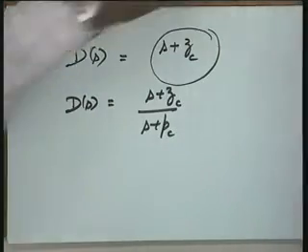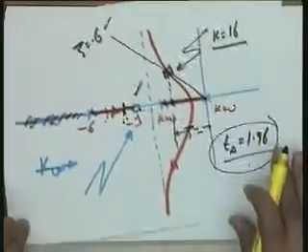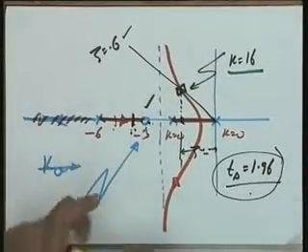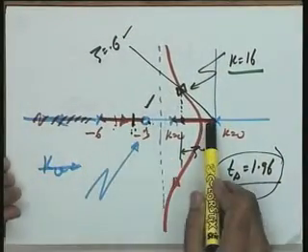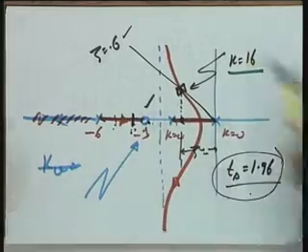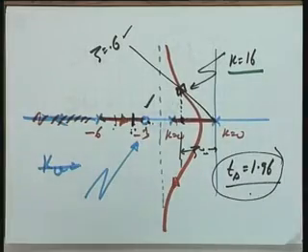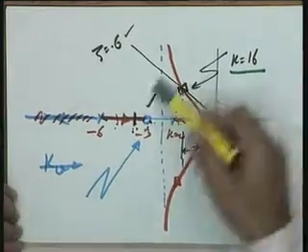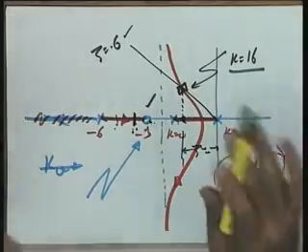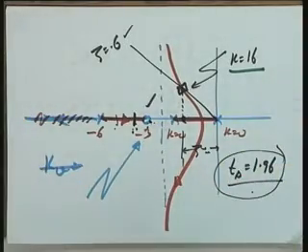Now let us see, where do I place the pole? If I place the pole in this particular region, the whole design gets disturbed. In this particular case, all these requirements which you have satisfied, the purpose of the pole is really not to help in the design. Your performance requirements on the steady state and the transient accuracy are satisfied.